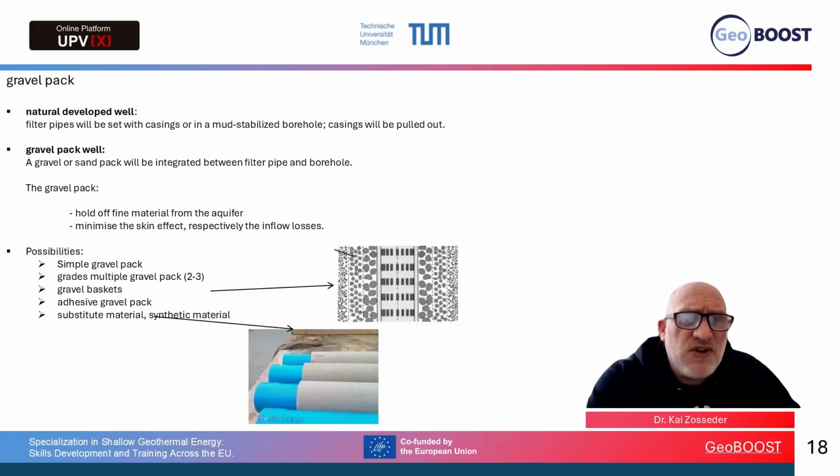So we talked about the gravel pack in the well design. What is the function of the gravel pack? You can have naturally developed wells. So you have to develop your well and make sure that you have a very good inflow into your well from your aquifer to your borehole and your filter section. But if you have a naturally developed well and an open hole well, then you do not need a gravel pack. Normally, a gravel pack is used.